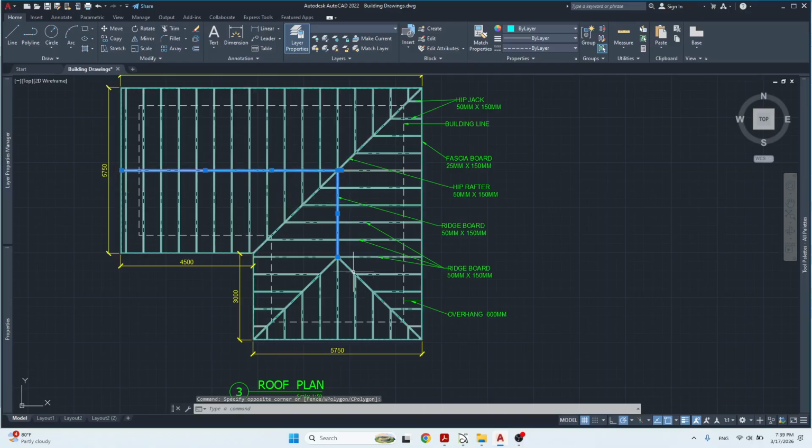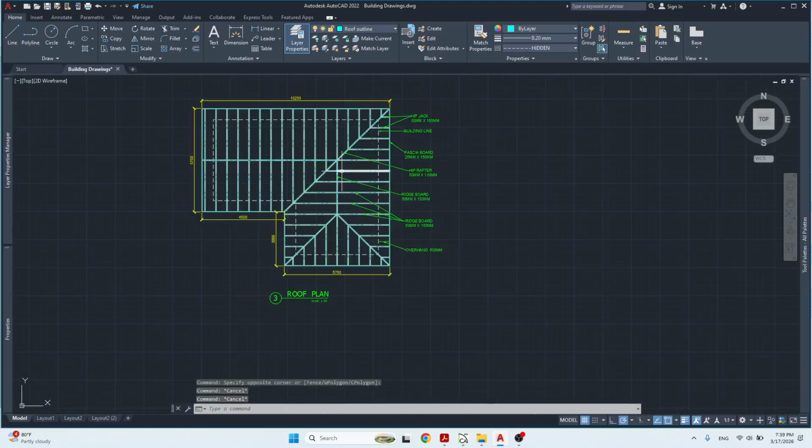So if these two hips meet at this point where the ridge starts, let's say it's, for example, 10 feet, then this ridge is going to be 10 feet high, and this other one over here, just because the two walls are the same, this ridge is also going to be 10 feet high, and therefore the two ridges would meet at that point right here. Okay, so that's pretty straightforward. Once the two sides are the same, then the ridges are going to meet at the same height.